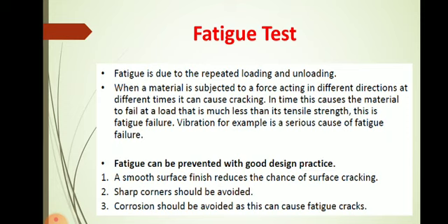In day-to-day application, consider any kind of motor, and at the end of that motor an application will be connected through a shaft. Whenever there is misalignment in that shaft and motor bearing, vibrations are created, and due to these vibrations cyclic loads act on that shaft, and due to that there will be fatigue failure of that shaft. So vibration is a major cause of fatigue failure.